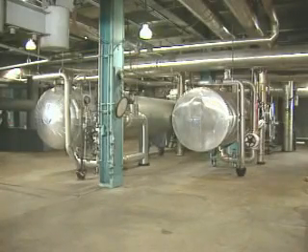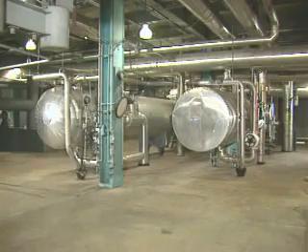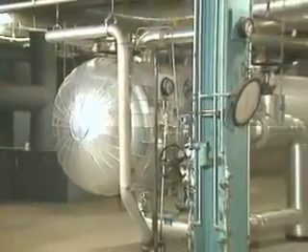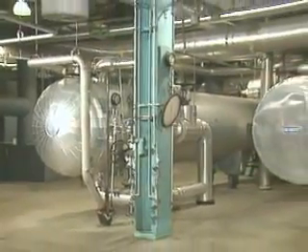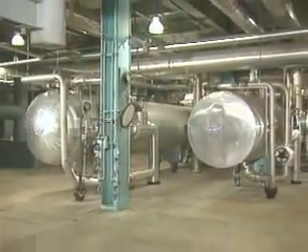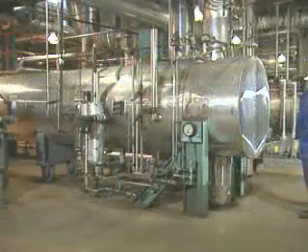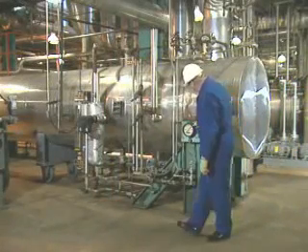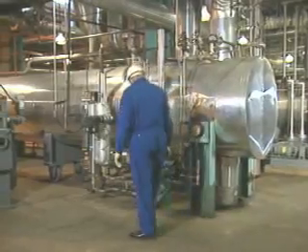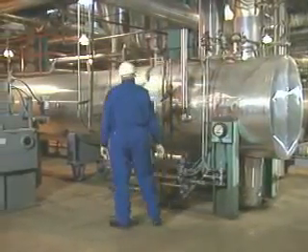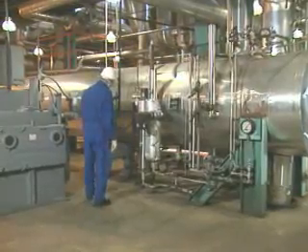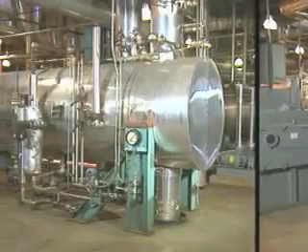A typical condensate and feed water system has several shell and tube heat exchangers or closed heaters. Some may be used as condensers, but most are used as low, intermediate, or high-pressure heaters for the condensate and feed water. The levels, temperatures, and pressures for all the closed heaters should be checked periodically during normal system operation to make sure that these operating variables remain within predetermined normal ranges.